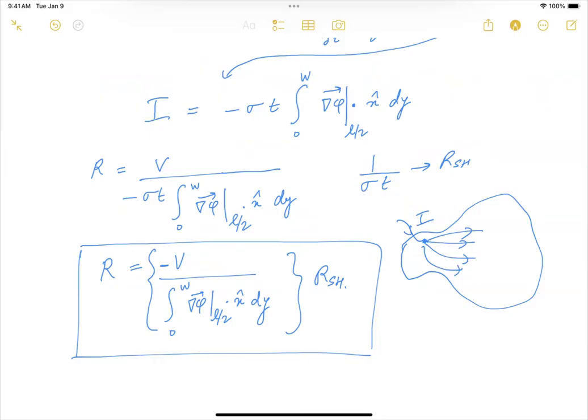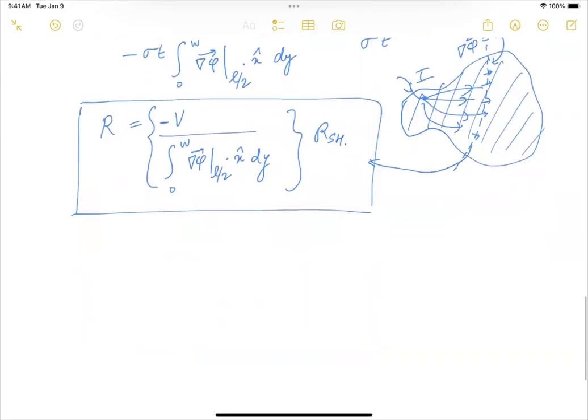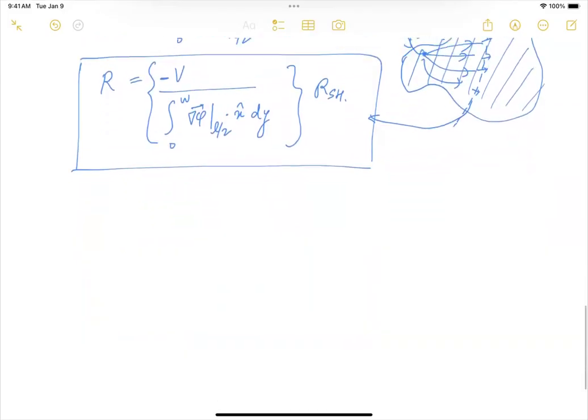But if you can calculate the Laplacian inside this metal subject to the boundary conditions, and then we use this Laplacian to create a cross section and calculate the current density at every location times the area and integrate it over this cross section, and we substitute that over here, then we can get the value of the equivalent resistance of this very complicated looking metal surface, a metal plane, right? So that is the general expression for the resistance.